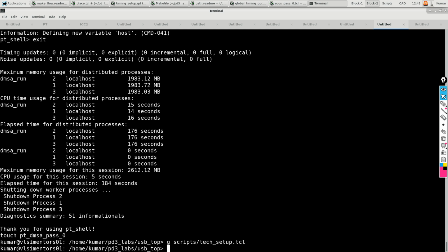Okay, so the next question is about full chip integration. Will timing be violating or not? Interface timings would be violating. Full chip means you will have reg-to-in paths and reg-to-out paths. They might be violating. You will get ECOs from the top level STA team.